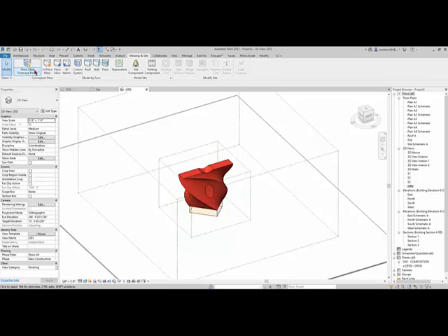It turned this on. So in the pull down, you have Show Mass by View Settings, and that turns the masses off in this view. If you have Show Mass Form and Floors, it turns it on for every view, so you'll be able to see it. So it's very helpful that it does that.